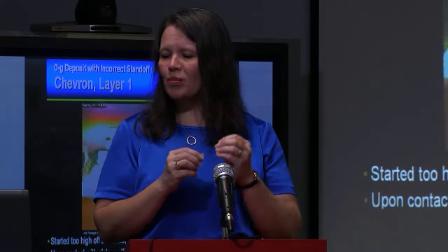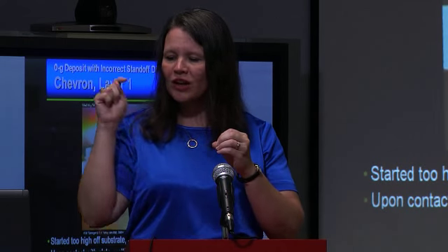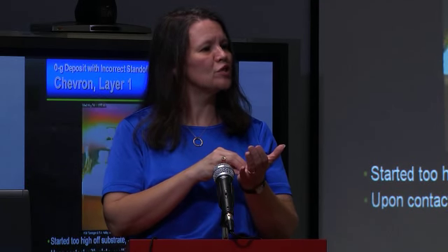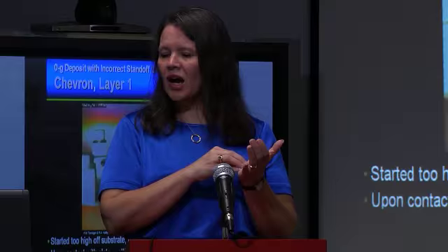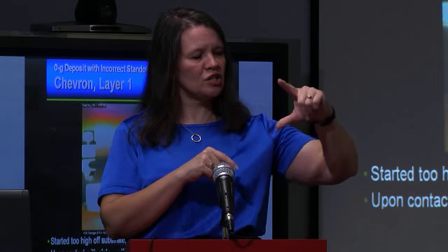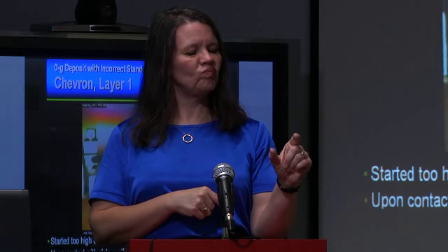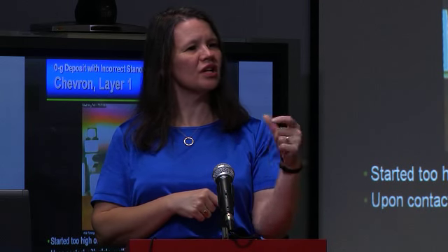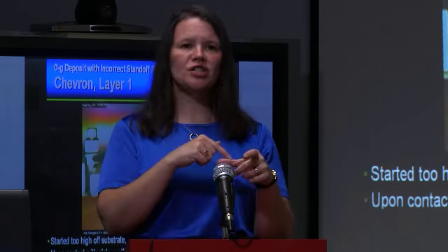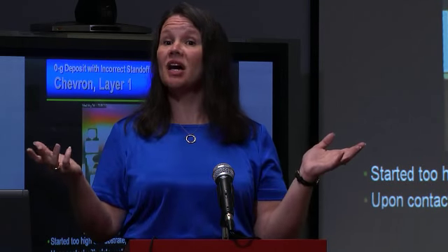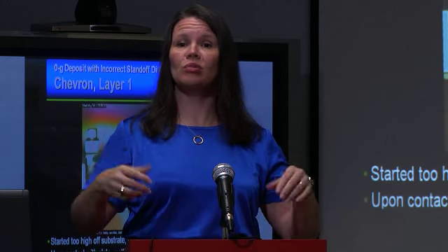So we're feeding wire. That ball is getting bigger. A little piece of the wire finally pushed through, and as soon as we got close enough to that base plate, the wetting forces pulled it down onto the plate. What we're building is a chevron, so just kind of a little 90-degree angle, and it's about 1.5 inches, maybe 2 inches on each of those two legs. And we traced over it, once going one direction and then coming back. And that's all we had time for in a zero-G parabola.